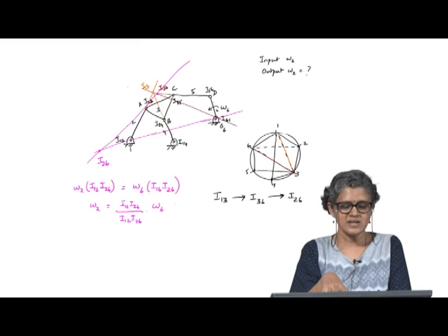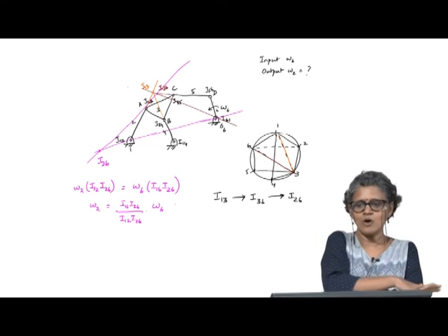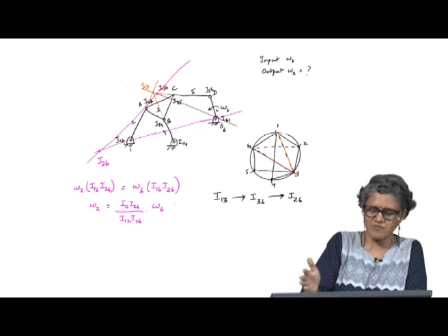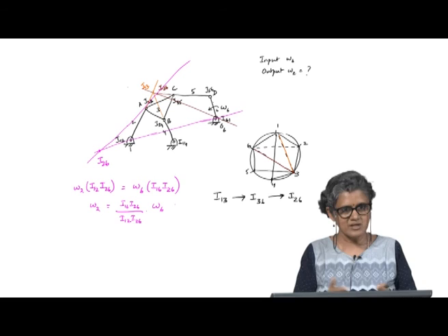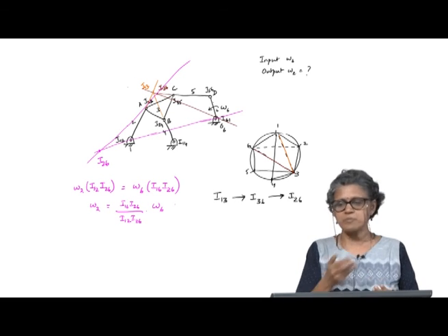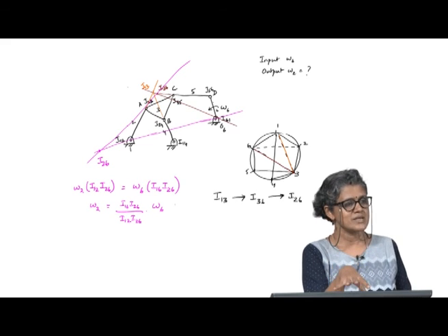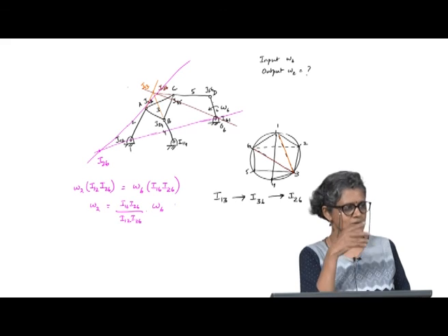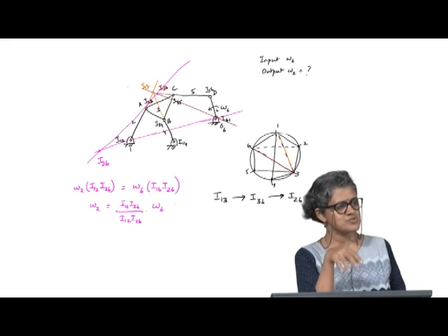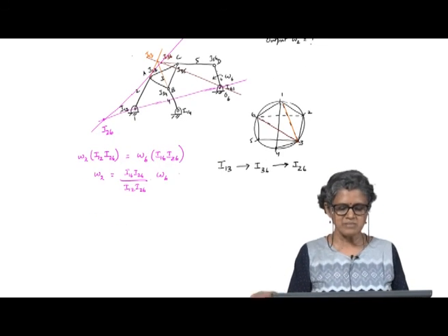But with instant centers, suppose the instant center is located out of the plane in which you are, when I say out of your working area on the plane, then you are in trouble. If you do not have a big enough sheet, then for a particular position you may not be able to do the velocity analysis. Again, it is okay if you want to just do it for specific positions. Graphical methods always are okay if you want to just do it for a few positions. Okay, if you want to do it for multiple, for the range of motion, you will have to go to an analytical method, and we will look at a couple more interesting methods. Okay.